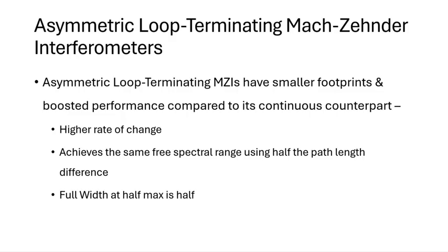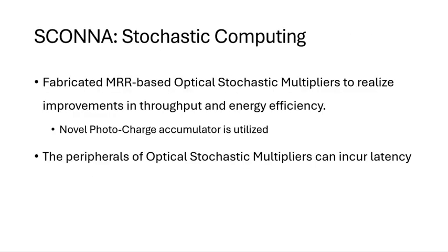The transmission spectrum can be tuned using DC coupling coefficients as the relative intensities of the even and odd resonances change. The main bandwidth limitation is the resistor capacitor time constant, and decreasing the capacitance of the modulators will further enhance performance. And the asymmetric Mach-Zehnder interferometer sensor permits the engineering of wavelength sensitivity and figure of merit independently.